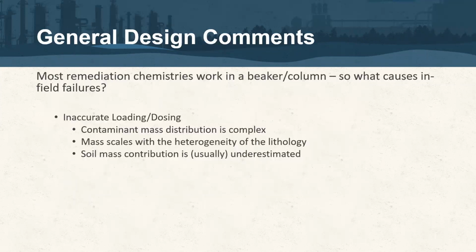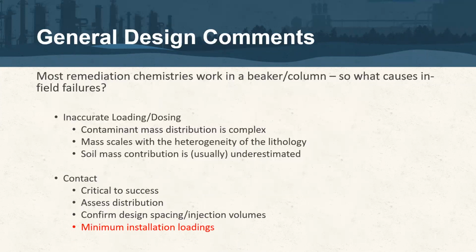And so my last comments here, and when it comes to design, right, most of this is going to revolve around dosage or shot volume or loading, as we call it. It certainly applies with any slurry, but it does apply with Fluoro-Sorb as well. And I'll point you to that final bullet point there, something we call minimum installation loadings. A number of the estimation designs or draft designs we've done for pilots, demonstration projects, even estimating for full-scale size deployments of Fluoro-Sorb via injection, we find that, in lab testing, probably about half of those sites, when we go through the evaluation, the minimum installation loading applies.